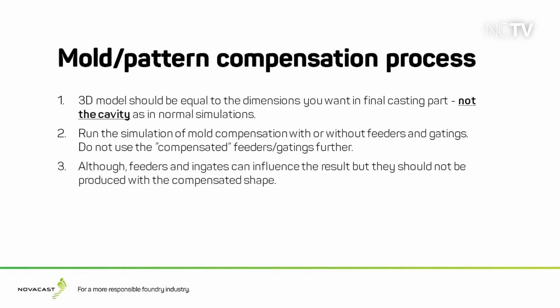So the process is like this. The 3D model should be equal to the dimensions you want in the final casting. This is not as it is for normal simulations, because then we are using the cavity, meaning that we have already added a percentage of dimensional changes for compensating the liquid contraction, the solidification contraction, and the solid contraction. That is what we need to do for normal simulations, but not for this one. Here you should use the final casting part as it should be sent to your customer.